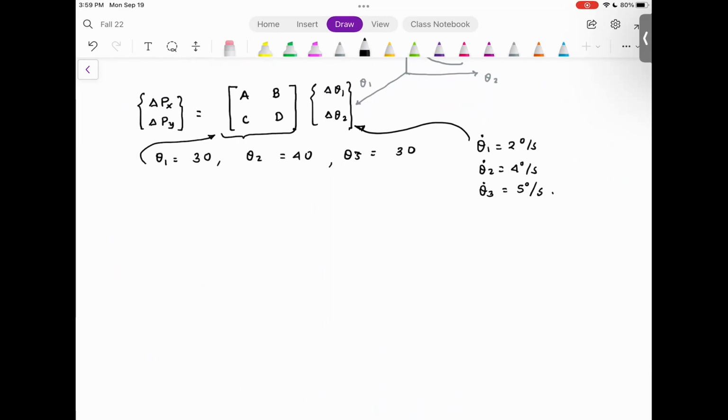So you said that if the robot has to move a larger distance, we take multiple snapshots. And so are we shifting the frame in each snapshot little by little to the final position? Yes. So basically you take the snapshot, and these equations will not be valid if you decide to take the angle here and velocity here. As long as your angle and velocities are in the same or next frame, that works.